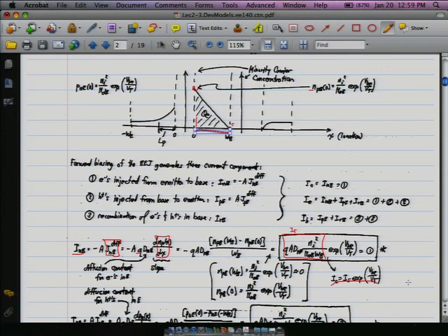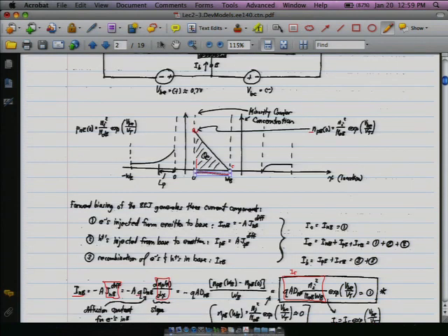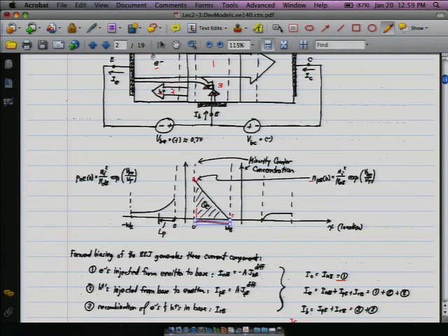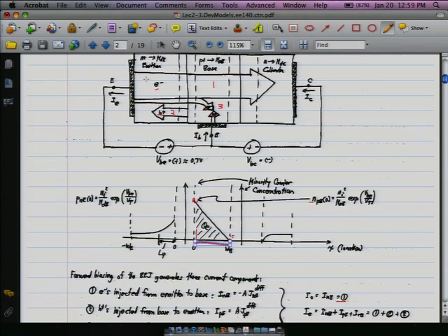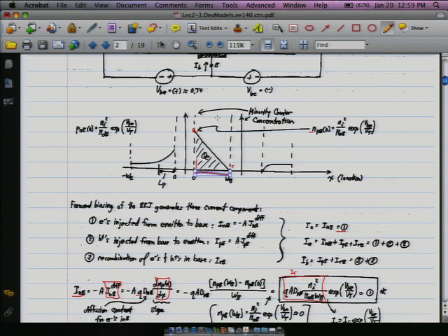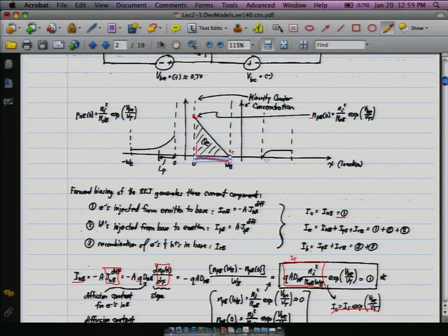If we go back to these number conventions up here, this contribution, remember we're talking about the flow through here, is what makes up the collector current, I sub c, which is one of the two currents we're most interested in. The other one is the base current, and that's a sum of the other two components that we'll go into now.